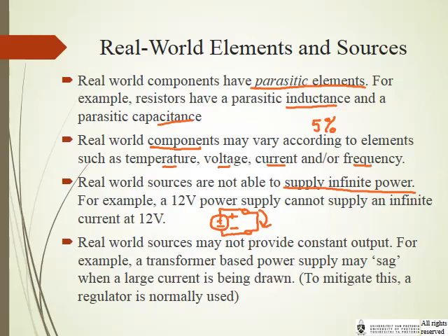Well, for one, this wire will probably burn out. Then this voltage source always has some small internal resistance, a parasitic element in the source. So there's going to be a voltage drop across that internal resistance, which is going to limit the current that can flow. So you cannot have an infinite current.